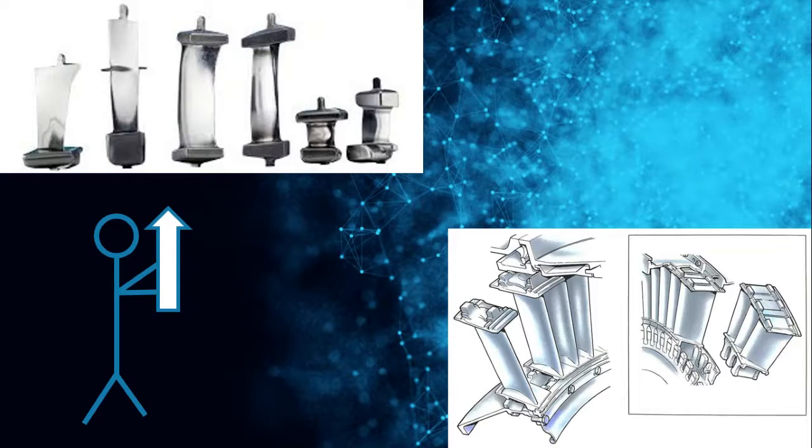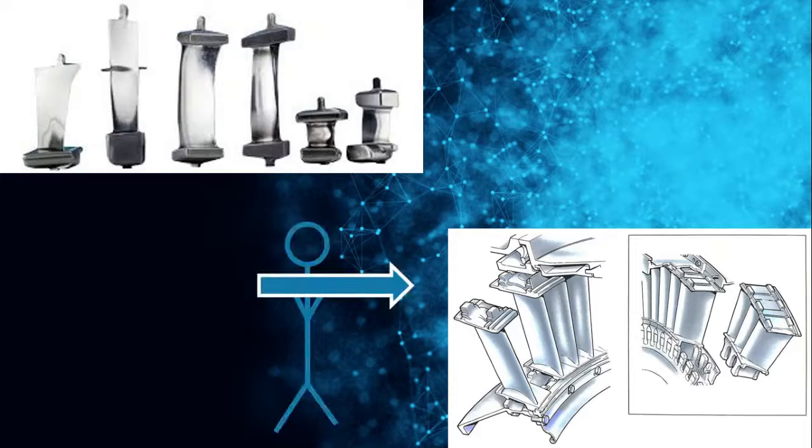Engine airfoils produce a lifting force that acts at right angles to the airstream and a dragging force that acts in the same direction as the airstream. They are made of nickel superalloy CMSX. Nozzle guide vanes direct the airflow into the turbine blades while converting pressure energy into kinetic energy. They are also made of nickel superalloy, but it's a different one, the C1023.